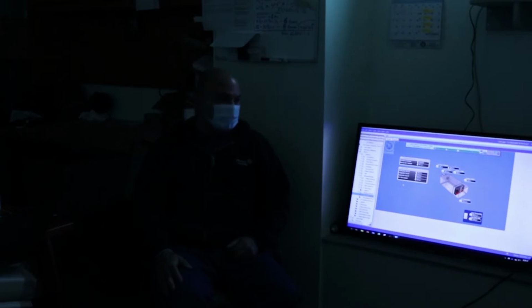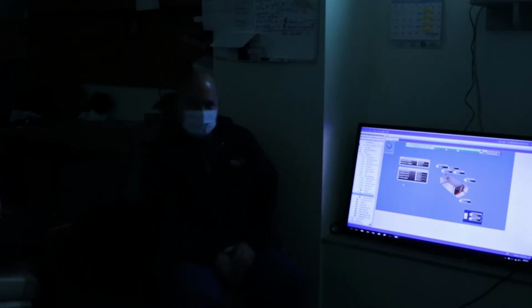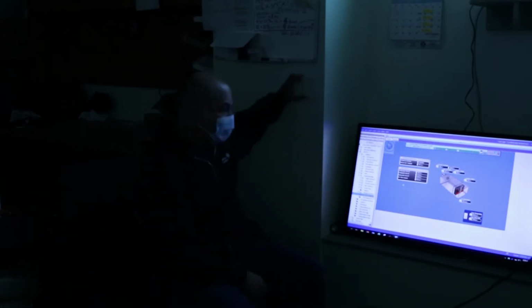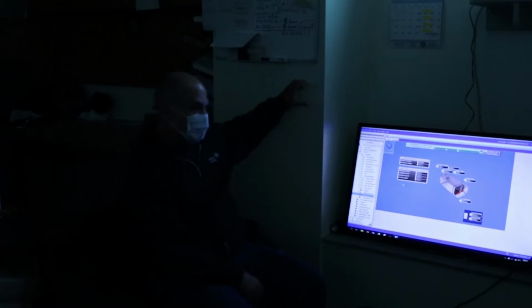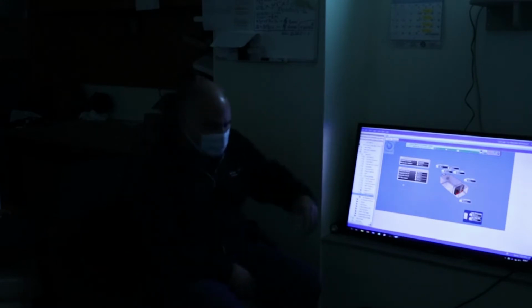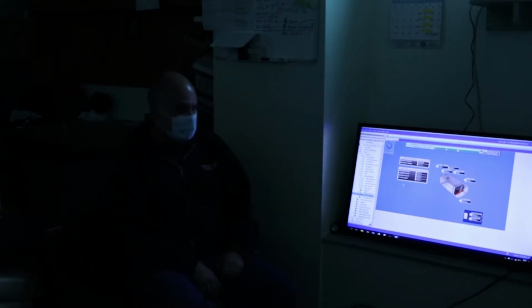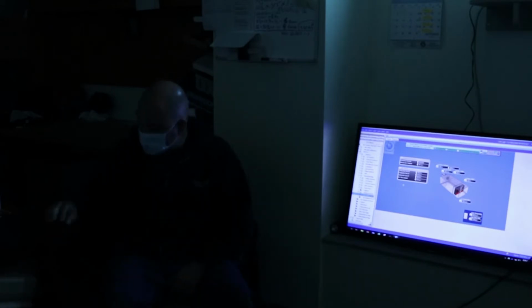The thermostat looks like a blank plate on a handy box, that's it. No adjustment, it's just the sensor. That's the only sensor you have in the rooms. Who can adjust the temperature? You can, from the BMS front end, that's it.